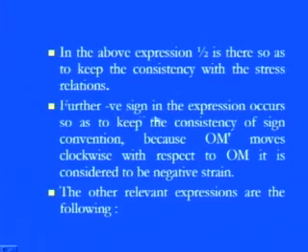Further, the negative sign in the expression occurs so as to keep consistency of the convention, because OM dash is moving towards the clockwise direction. Whenever the shear stress or strain is there, if the object is tending to move clockwise, the positive sign is used, while OM is always considered negative because it is tending to move counterclockwise.